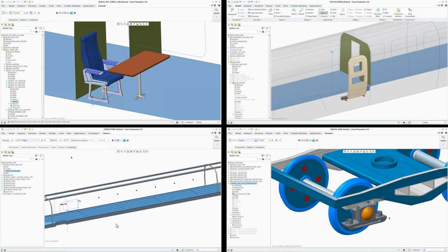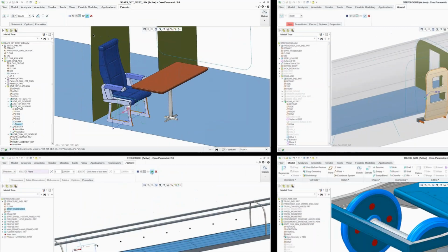But because this is referenced off of the geometry that I published out, if there was a design change where we only had space for 6, that's going to update accordingly, and our whole model isn't going to explode. I'm sure there are a lot of people who don't have the design intent down, and they've run into instances where a simple design change like that, changing the instances, has their whole model blow up in their face. And that's what we're avoiding here.